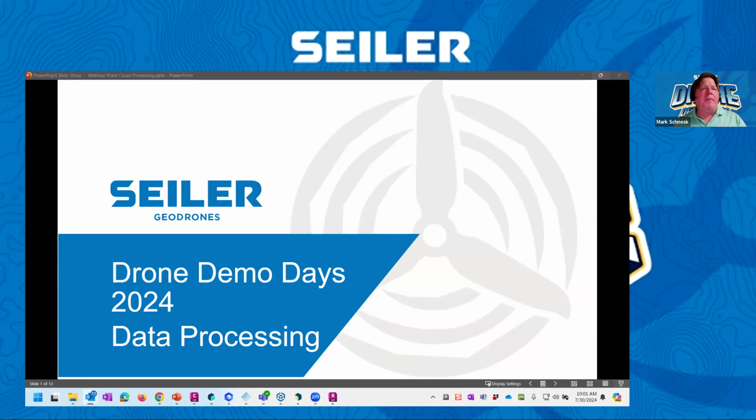All right. So we see all this data these drones have flown. We've seen the data collected. We're doing two different things. Typically for these aerial UAVs, we're collecting either photogrammetric data, taking photos of a site over a nadir site, or we're collecting LiDAR data, which is an active scan data. So with a variety of different tools. Today we're going to say, okay, everybody's seen these drones fly at their drone demo days. Let's go through some processing options. What is it we're exactly going to get out of this data?